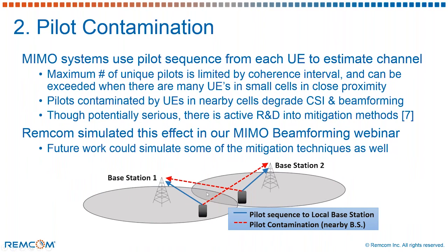Last, we have the orthogonality of channel responses. MIMO relies on channel responses having sufficient diversity that different techniques can be used to improve the signal, whether it's beamforming, diversity, or any other spatial multiplexing kinds of techniques. There are two traditional methods that are used to characterize a channel. They're called the rank, which equates to the number of potential streams that can be formed, and the condition number, a ratio that characterizes the ability to multiplex over multiple streams.